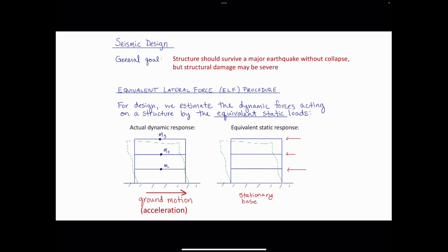So the use of the building plays a big role in all of our load designations, but especially with earthquakes. So when we are figuring out the loads that we're going to use to design beams and columns and floors and diaphragms and walls, we have to think about how to relate these static forces to the actual event, right?